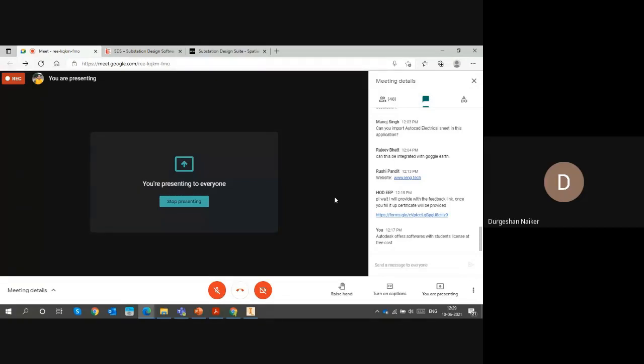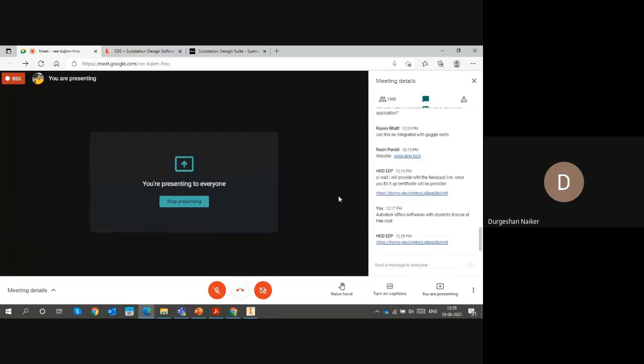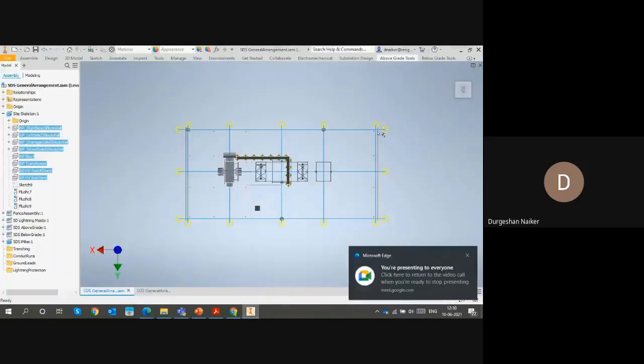And the other question, I think there are a lot of questions regarding rolling sphere and all that. If someone is interested, they can book another time separately, and then we can answer the questions. But just generally speaking, it's based on your striking distance. What is your rolling sphere radius? If it is 20 meters, given by the standards or by the utility, that means the cloud can come closer to the substation, and it can probably damage the device that you're trying to protect.